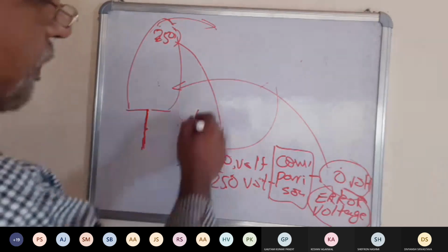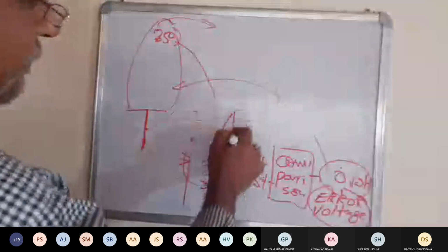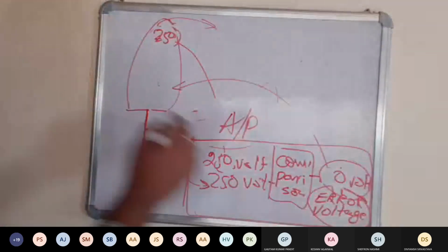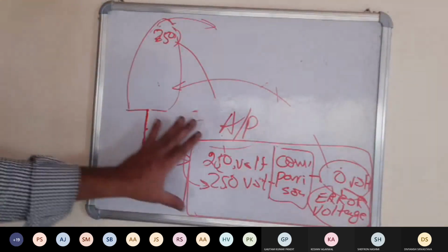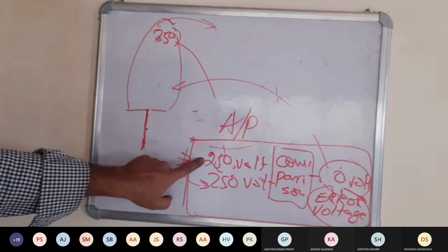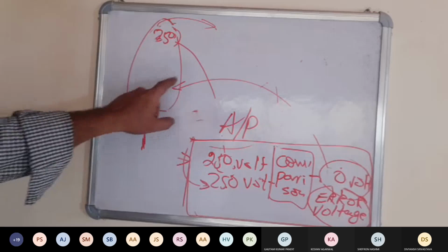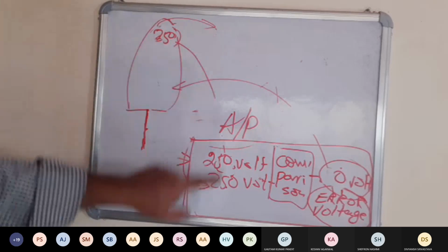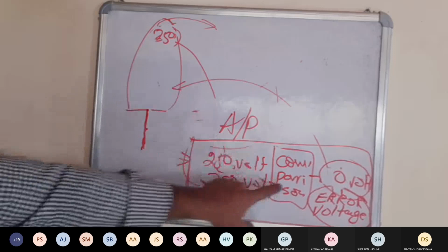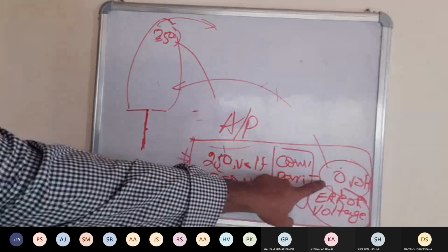So in the autopilot system, this is what is happening in general. It is actually very complex, but in general this is all there is. The heading information is converted into a voltage. The course to steer, CTS, also gets converted to a voltage. There is a comparison between the two to find out the error voltage.